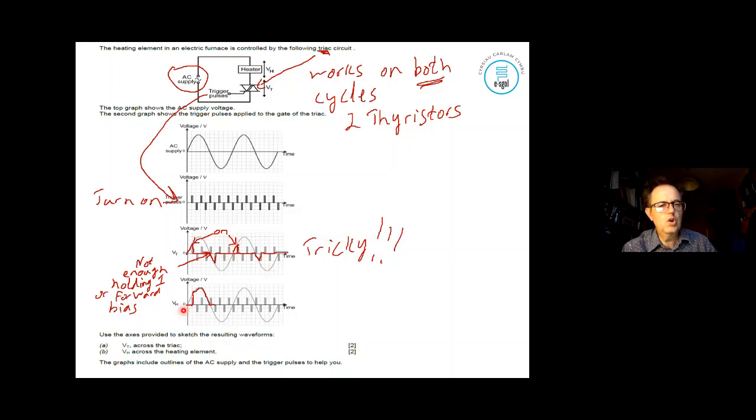As we said, the load is going to be opposite to your thyristor. So the load will get the voltage once your thyristor is off. Sorry, when it goes on, which means there's no voltage across it. So your voltage across the load will increase at those points. Those graphs go hand in hand together. They're always opposite for thyristor and for the load itself. The important thing with this one is that the negative cycle was being used.